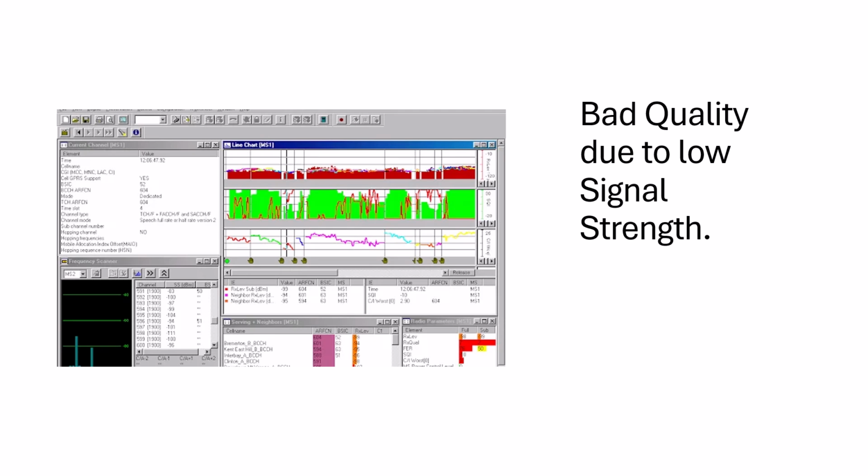Users can switch to devices with better RF performance or use an external antenna connection if the coverage is poor indoors or in remote areas. By tracking the root causes, whether it is distance from the site, physical obstruction, suboptimal cell planning, or interference, operators can mitigate low signal strength issues, yielding better call quality, fewer dropped calls, and improved data throughput.